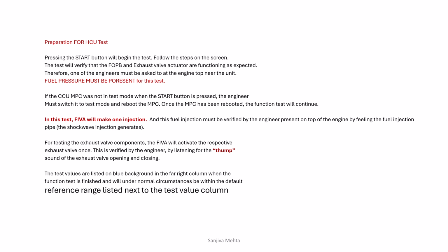Therefore, one of the engineers must be asked to stand at the engine top near the unit, whichever unit you are testing. Fuel pressure must be present, of course. If one injection is made, the duty engineer standing there will be able to hear the sound. You know how the injection takes place. We check the fuel pipes and know that the unit injection is taking place. If the CCU MPC was not in test mode when the start button is pressed, the engineer must switch it to test mode and reboot the MPC.